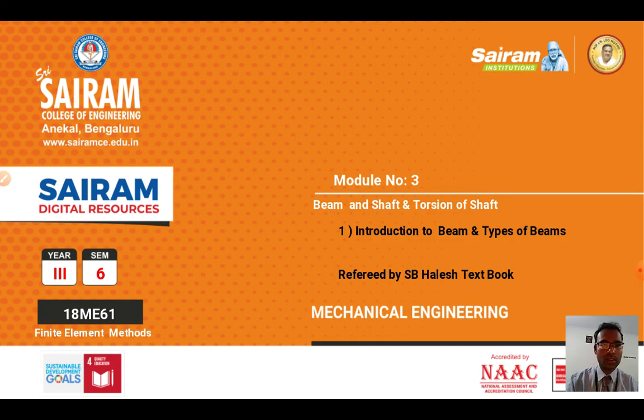Just to understand from this lecture video, a beam is a long slender structural member whose length is considerably larger compared to its width and breadth. Such a component we are going to call a beam. Depending upon the given load, shape or support, beams are classified in different ways. For your syllabus: simply supported, cantilever beam, overhanging beam, propped beam, and UDL, UVL. On these beams you will have numerical problems, so you need to study those beams.